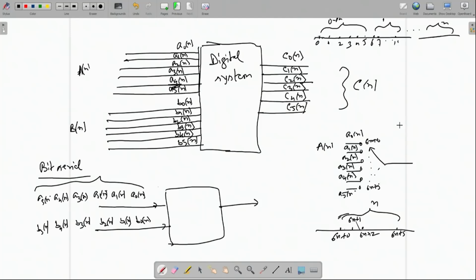But what I am getting here, as I told you, earlier my digital system was doing some processing on A0 and B0, giving the result C0. Parallelly, another processor A1 on B1, giving the result C1, and so on and so forth. So, 6 times I have got the same repetition, or I mean there is an operation which was done 6 times parallelly. So, hardware and power were going up 6 times, but here every bit clock I will take only one A0, one B0 and do some operation. So, I will not require 6 times hardware, it will be compressed.